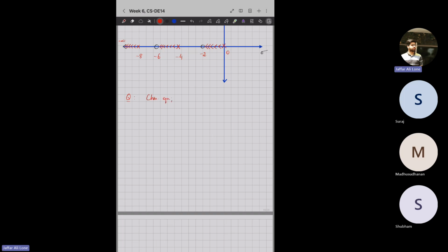Characteristic equation is given. I told you whenever we talk of root locus, we talk of open loop transfer function. So 1 plus k into 1 divided by s into s plus 1 into s plus 2 is equal to 0. So clearly we can see from here, this is my g of s, h of s, because my characteristic equation is 1 plus g of s, h of s is equal to 0. And this is the open loop part, and this is what I need.